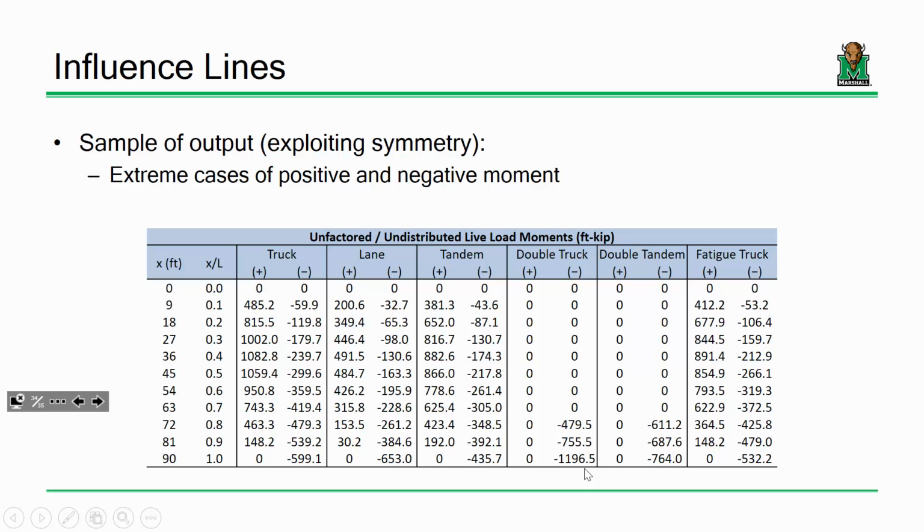What I do expect is that given this longitude, keep in mind, this is all longitudinal data. This is just taking the truck and moving it down the bridge like so, right? This has nothing to do with taking the truck and moving it this way. We haven't even gotten there yet, okay? But this is just taking literally a simply supported beam, and taking that truck, taking that lane, and generating maximum force effects at every 10th point. It's our responsibility to combine it appropriately and distribute it appropriately, and that's where that transverse placement comes into play. That make sense?